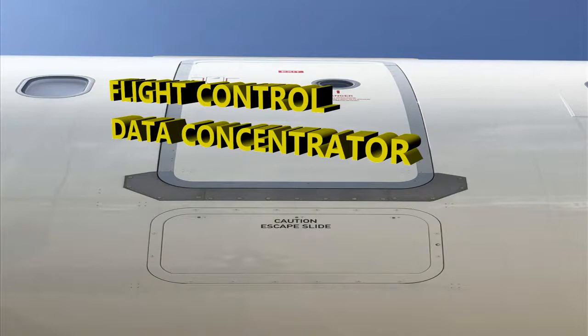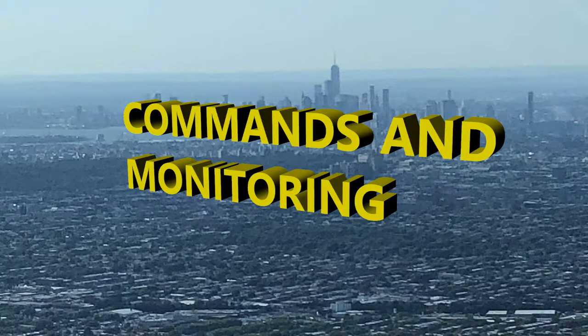If the aircraft configuration turns out to be in an unsafe position, then the flight control data concentrator is going to execute certain commands where the spoilers are not going to be retracted, and the trimmable horizontal stabilizer, for example, is not going to be in takeoff range. So just a few things there if there's something wrong, or an unsafe configuration.